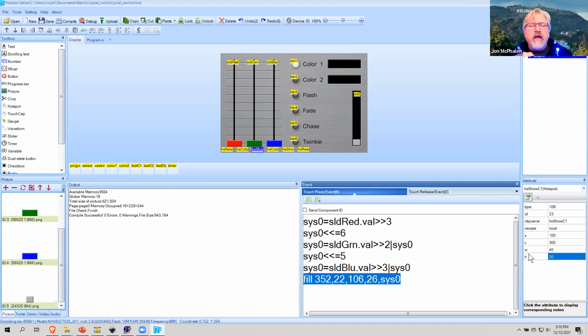If you don't have that clock module plugged in, go into the setup method, because I pre-built this code for the whole thing. You'll find start methods for the EEPROM and the RTC. Comment those out because they may be snagging since that thing's not there. Mine's not working with just this. Yeah, go into the setup program, comment those out and retry it. I bet that's it, because it's looking for the I2C line to be pulled high and it's not. John, I didn't have that hardware installed and I didn't have an issue.